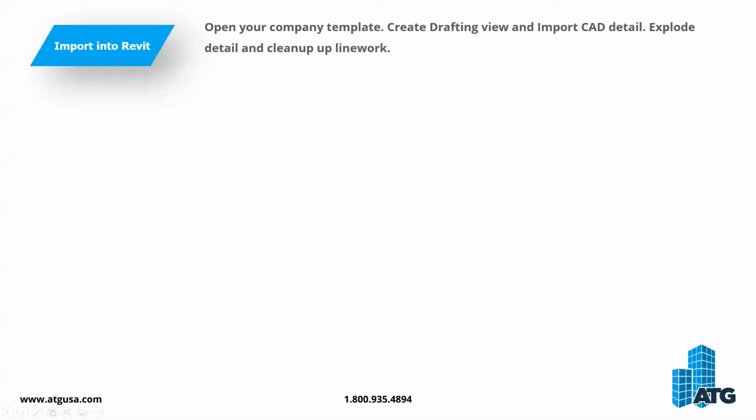So when you import it into Revit, the best practice is to create your new detail in a standalone Revit template. Don't import it directly into your model, because again, you can create issues. If you create a new drafting view in a new template, you can do this multiple times.